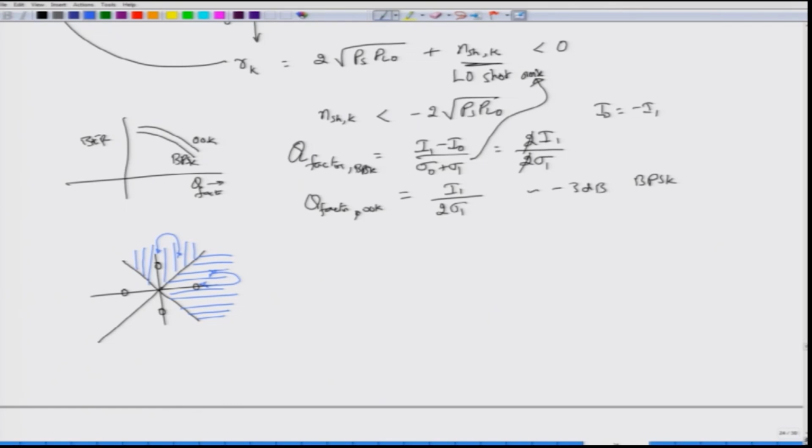Okay. You can calculate the error factors over here, but what is interesting to observe is that if only phase noise is present, then the phase noise margin of error would now have been reduced from 90 degrees to 45 degrees. Okay. This is very important. So, you now cannot go more than 90 degrees. So, 22.5 degrees on this side, 22.5 degrees on this side, I think that is what 45 by 2 is, and roughly you are going to get 45 degrees up here.